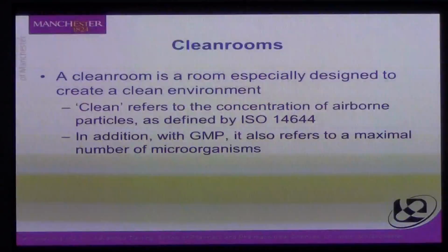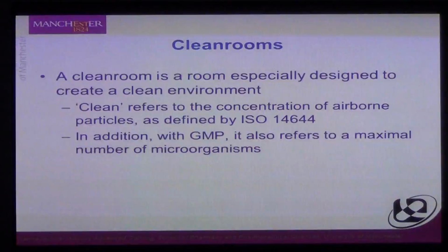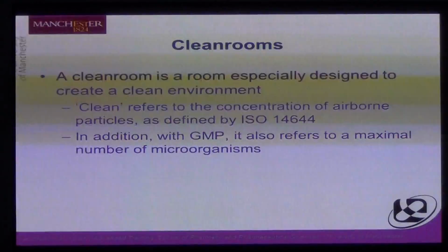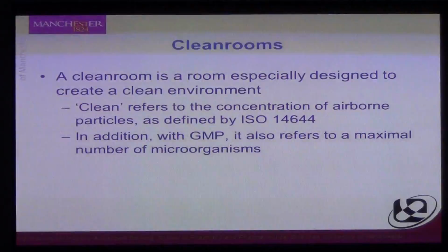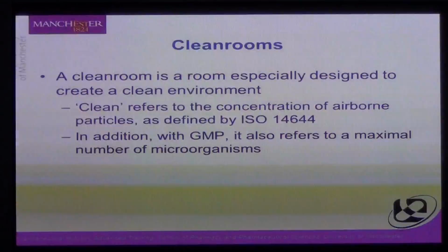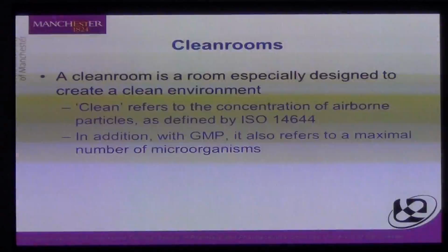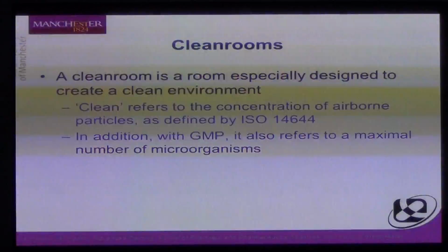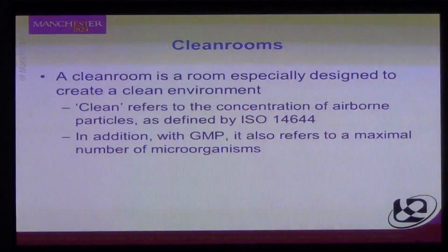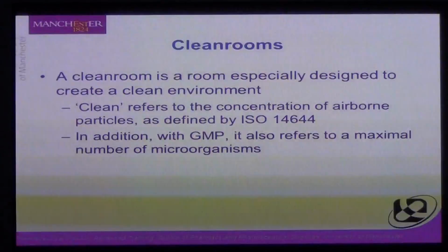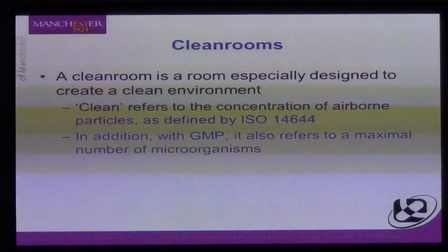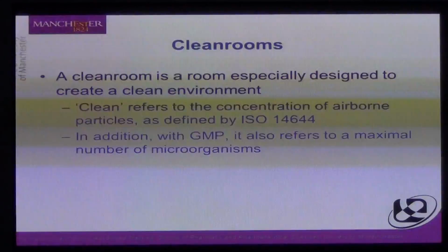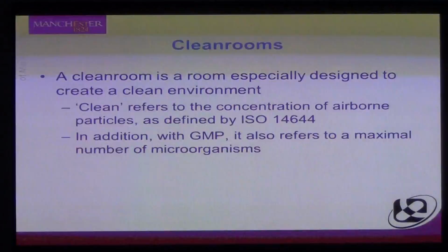So a clean room is a room that is especially designed to create a clean environment, and clean is defined purely by the concentration of particulates in a given volume of air. That given volume of air is 1 cubic metre, and that's laid out in an international standard on clean rooms called ISO 14644. That standard applies to the electronics industry as much as it applies to the pharmaceutical industry. Additionally, GMP also requires certain limitations on the maximum number of viable microorganisms permitted, so it overlays the core clean room definition.